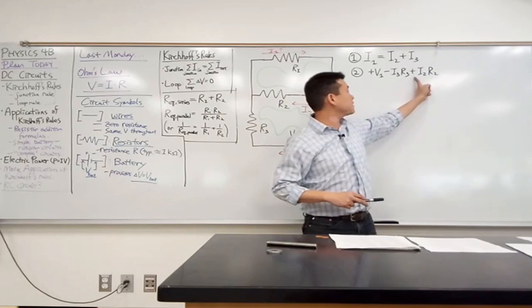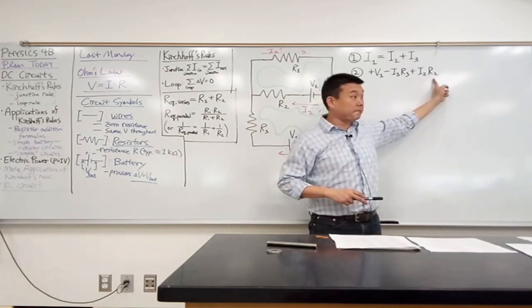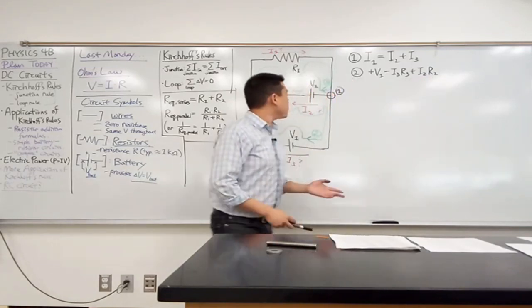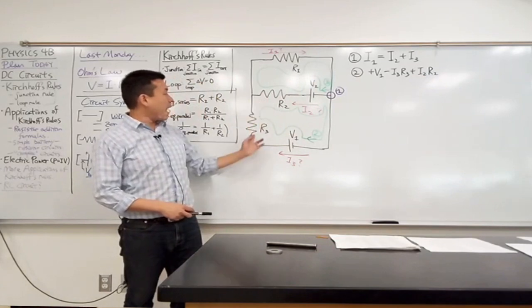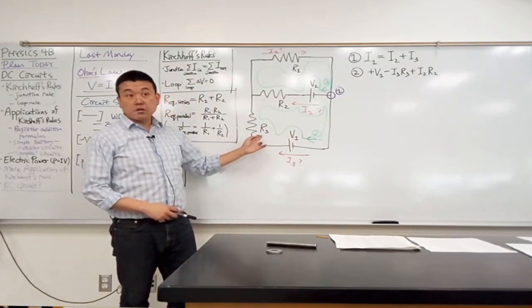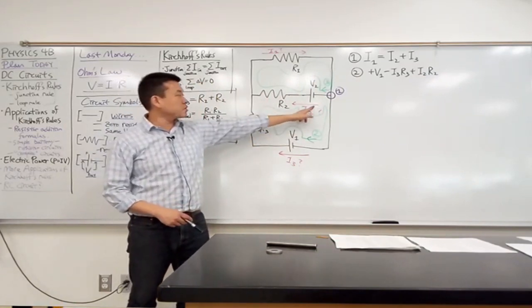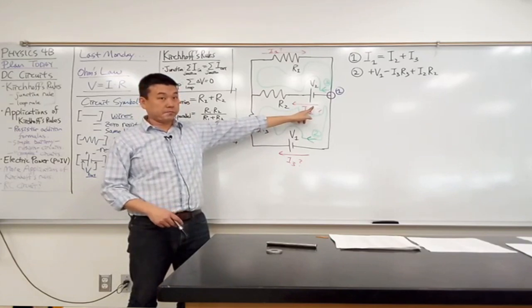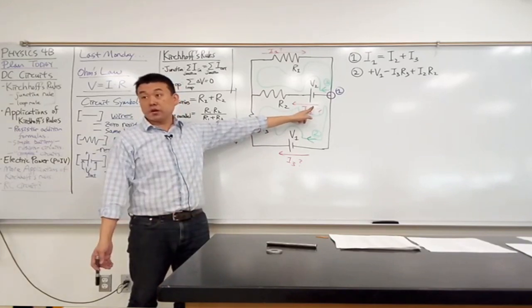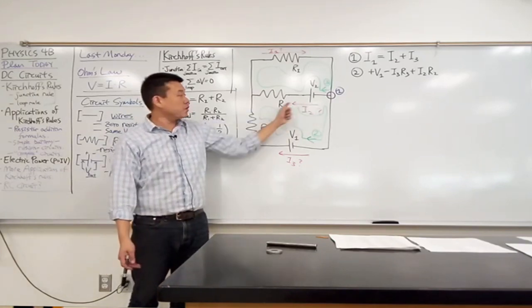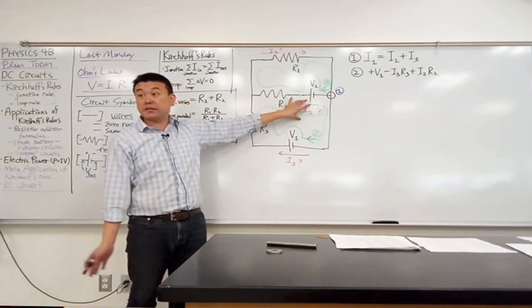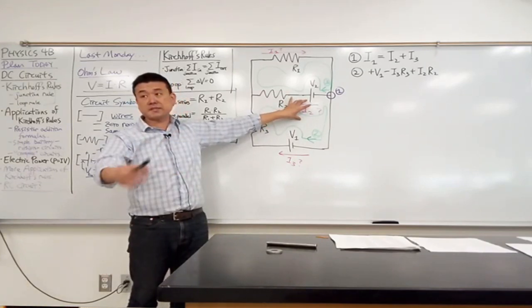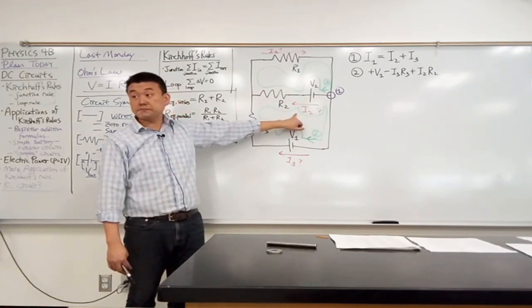So this expression still would represent the voltage drop. So when you're trying to figure out the rise and drop of voltage, you worry about what direction of current you labeled, not what is the actual direction of current. It's the directional current that you labeled that overrules everything else. Because you're trying to be consistent with the direction that you picked.